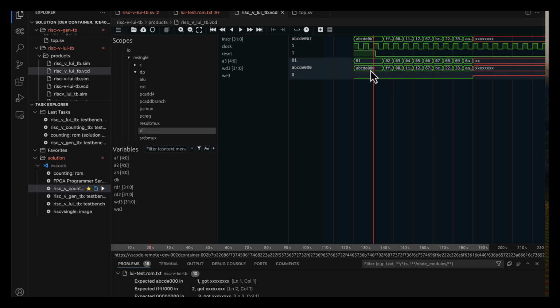So I had what I wanted to store being sent to the right place, the where I wanted to store it being sent to the registers as well, but I was never actually doing the store-it-now sort of thing. I wasn't properly configuring my write enable. So now I would go back to my Verilog and kind of work backwards. I know what I'm missing. I need to figure out the right place to actually get it to do that write enable.